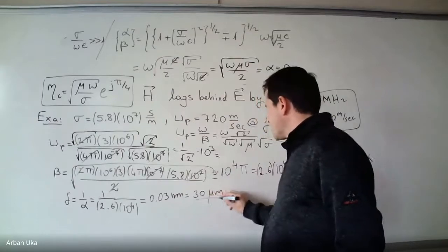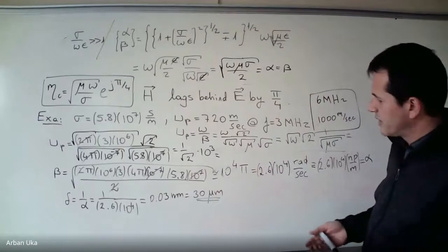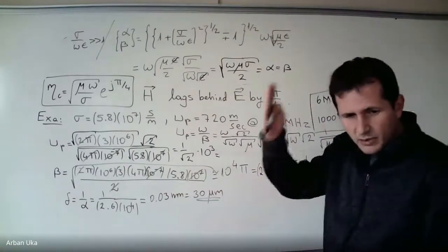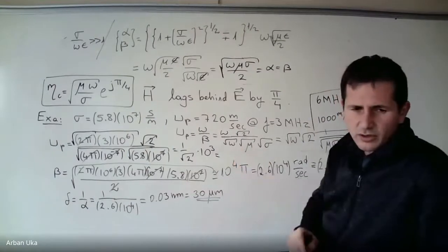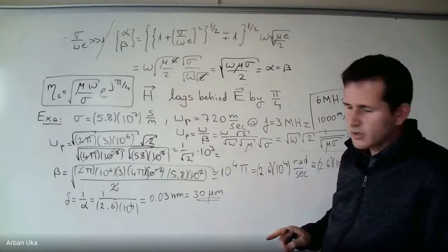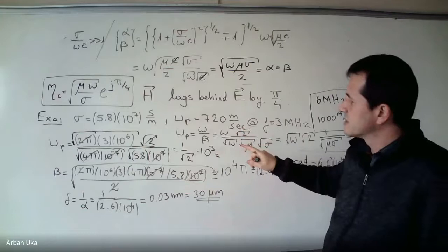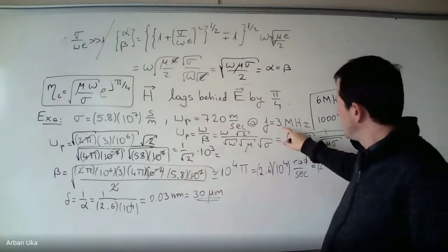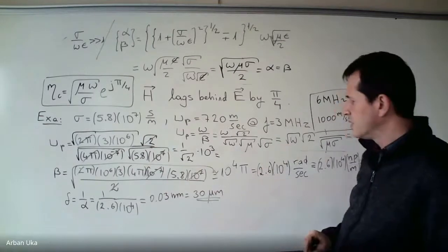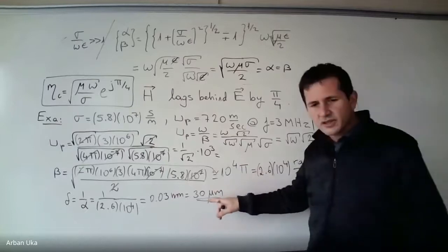Okay. So to see the distance where this wave is going to penetrate, you need a microscope. So if you pick up your hair and put it under a microscope, the thickness of a hair is between 30 to 60 micrometers. So this is how deep this will go into this metal piece. So at 3 megahertz, this will penetrate only a hair-thick line of material. Of course, it's not exactly this much, right?